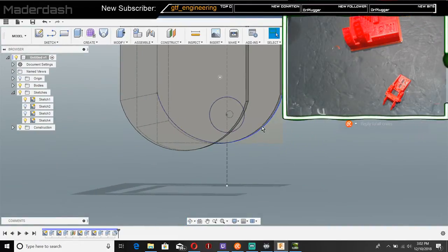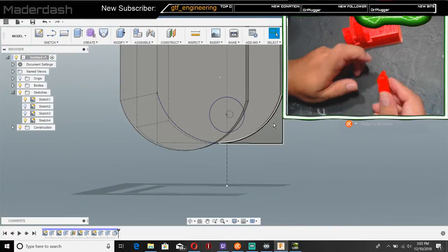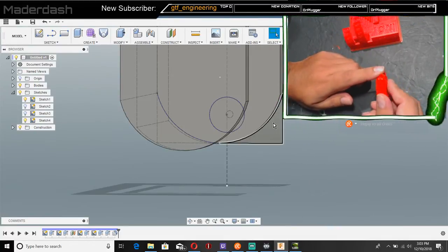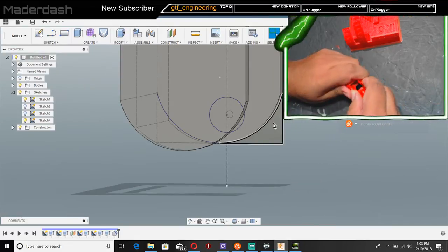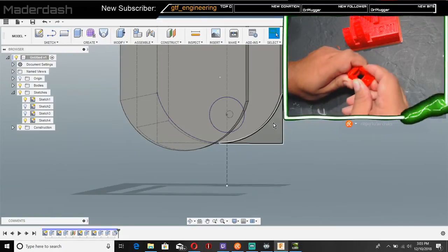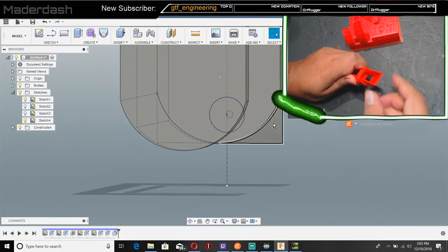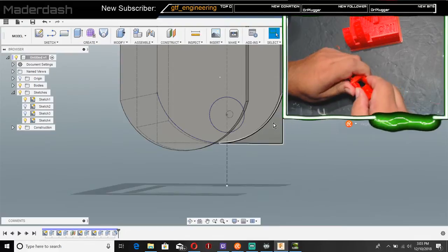See, mine are rounded. See that? You see my edges are rounded. Theirs are kind of pointed. You see they have a point on theirs, and the points are what's catching up. The point is stopping it from moving. I don't know if you can see that in there, but the point is stopping it from bending. See, it'll only go so far and the point stops it. So it's actually a design flaw.